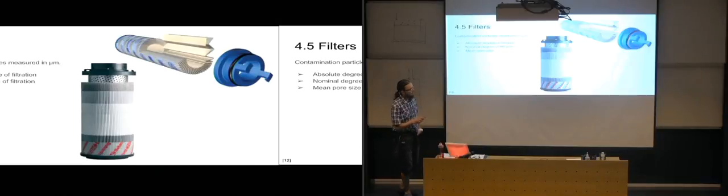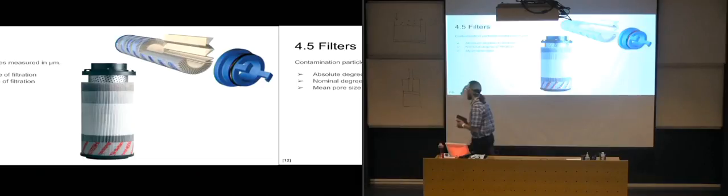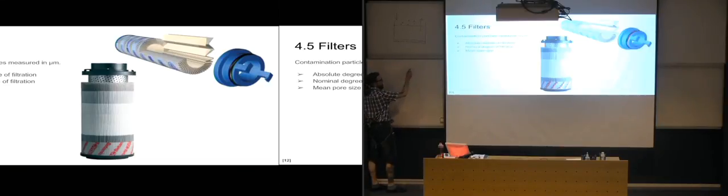In the case of these oil filters for car engines, you would see basically at the top part, one of the last things they put in there was, just do a slight drawing here. It was the part that was being stamped out all the way in the start, which was a circular plate that was placed on the top, and it had a hole in the center, and then it had several other holes going around. And the hole in the center is where the contaminated oil goes in.